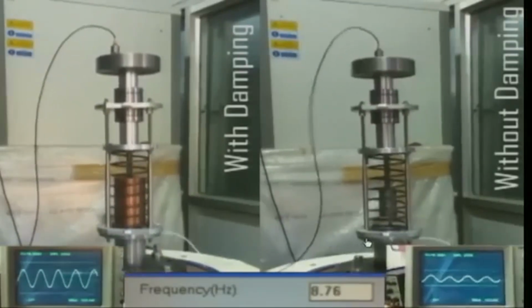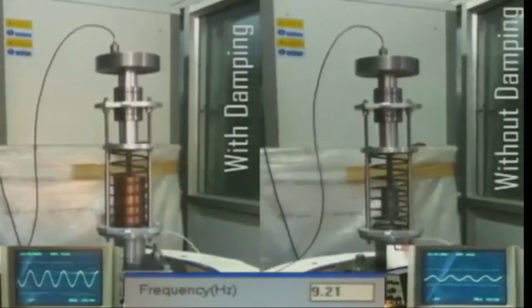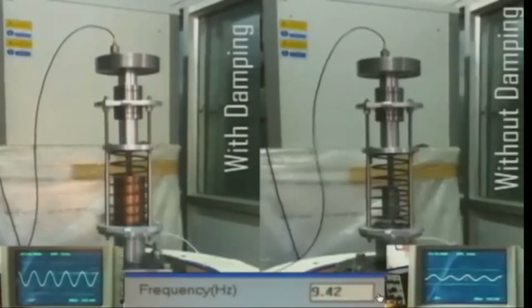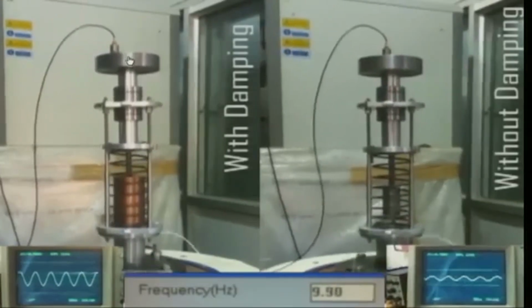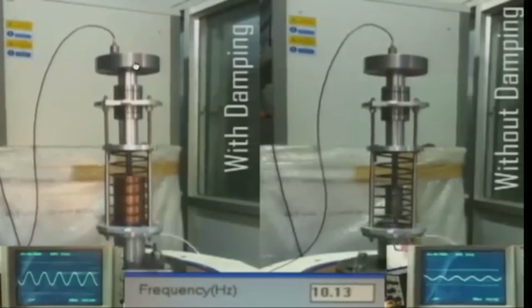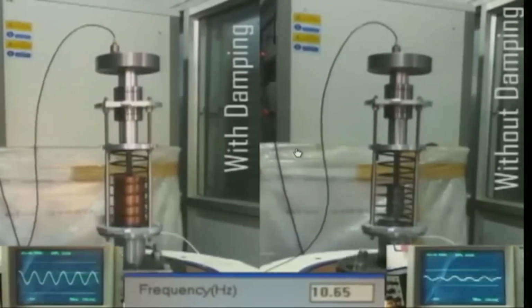As you increase the frequency, you may come across a situation where this will be even more vigorous here. On the other hand, you will see that with the damper there will be hardly any, as I told you that the damping is very important close to the resonance.